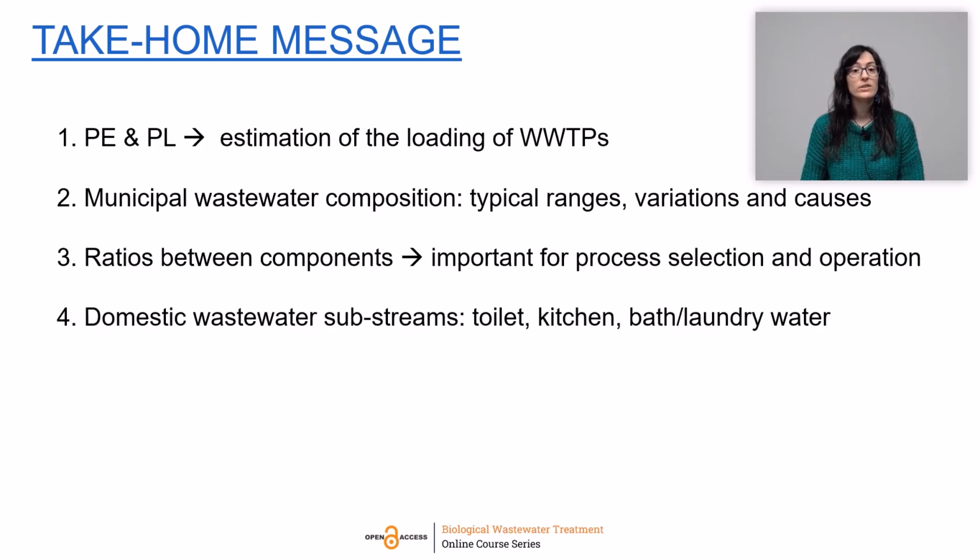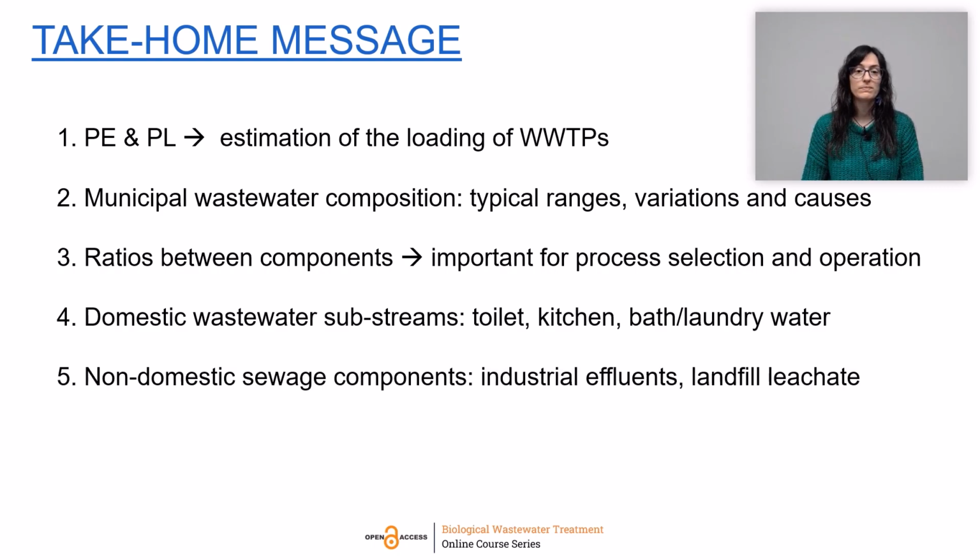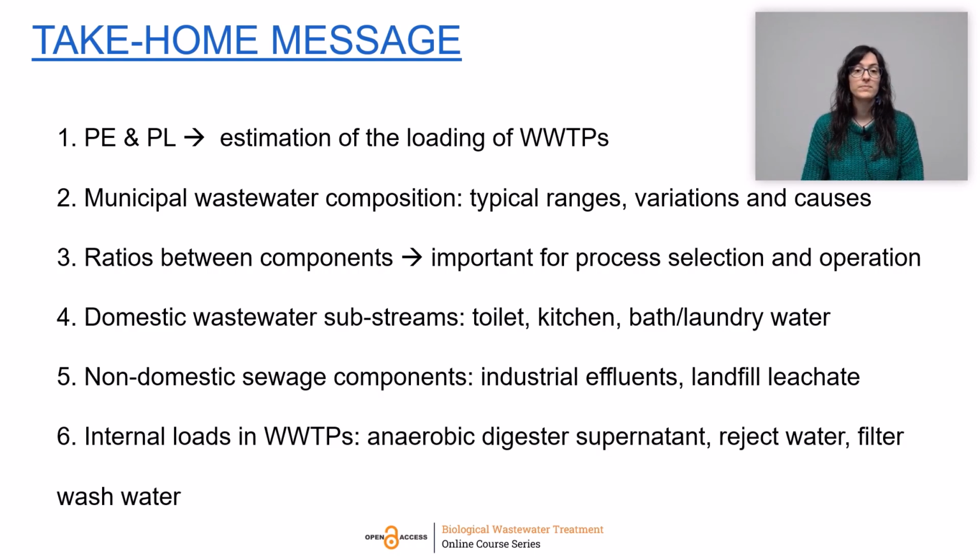We have dived into the domestic wastewater substreams, being toilet, kitchen, and bath or laundry the main contributors for the wastewater. We have also discussed the non-domestic streams, which are mainly industrial effluents, and other streams such as landfill leachate. And finally, we have also seen which streams produced internally in the treatment plants can also contribute to the load that needs to be handled. And these include the anaerobic digester supernatant, reject water, and filter washing water.